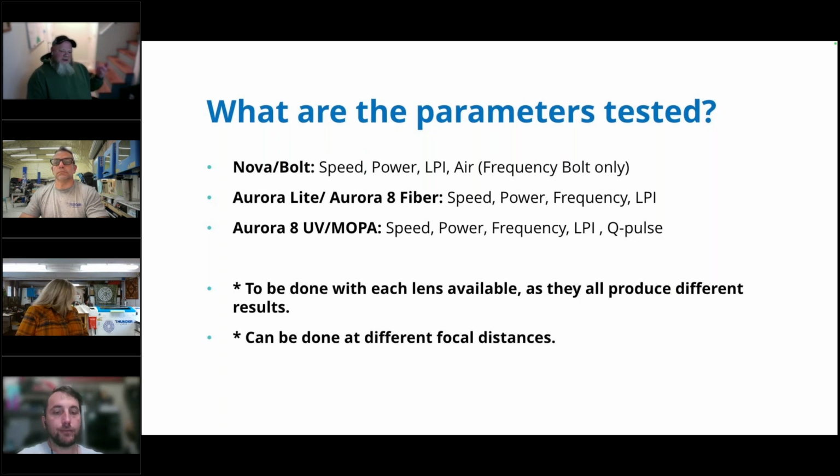Are you using a 2-inch lens? Did you want to try it with a 1.5, or test your engraving with a 1.5? You may have a reason to use a 4-inch because of a bowl or something. So you have to be able to test those with the different lenses to get your different settings, because each lens is going to change how a graphic looks when it's engraved on a specific material, and we've seen that over and over again.